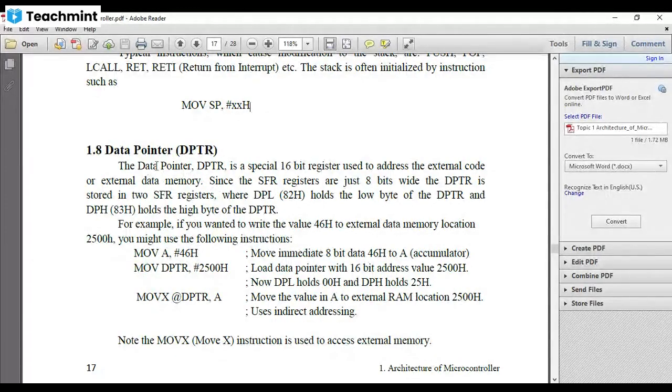Okay, it is DPTR. Now this DPTR is also one of the SFR. It is a special function register, but it is 16 bit, but our microcontroller is 8 bit. That's why the data pointer has two registers, that is the DPH and DPL. And we see in the special function register table that there are two registers. DPL has the address of 82H and DPH has the address of 83H, and combining these two happens one DPTR 16-bit address there.